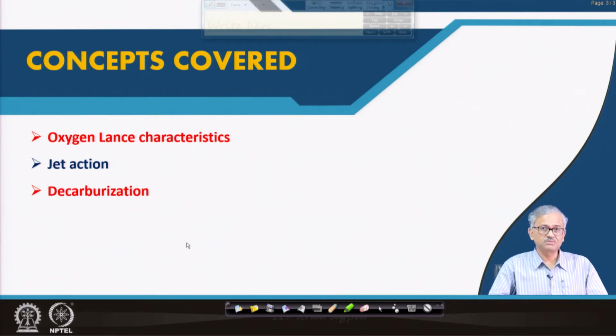So decarburization has a very important role in LD steel making, because it has to continue to the end such that you can keep the foam and emulsion stabilized to the end of the process, because in the emulsion only you have a tremendous surface area in the slag-metal interfacial area, where kinetics is fast because of that. So the decarburization reaction has a very special importance in LD steel making.